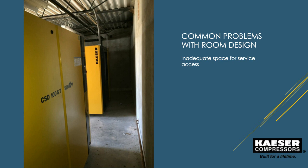You're not going to be able to service the equipment in an easy way in this particular facility, in addition to the fact that you have zero or limited ventilation as well. Further, you want to make sure that your electrical cabinet can open fully and that there's space for you to move around it should any issue arise. So getting back to not just adequate space for service, but safety as well.